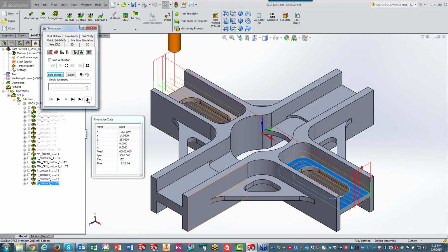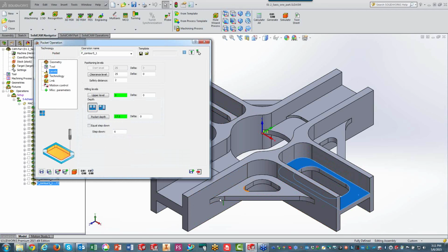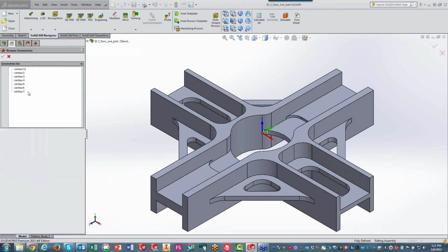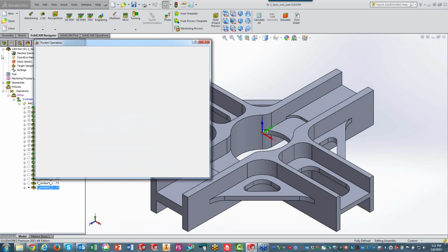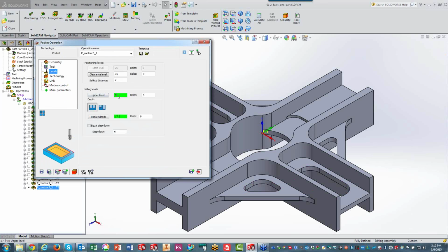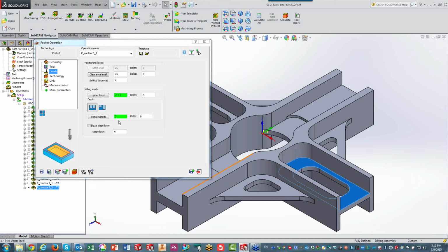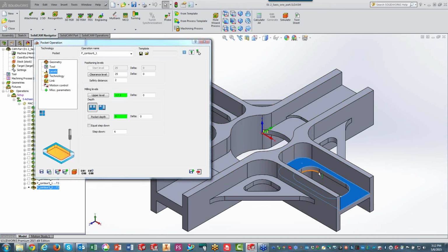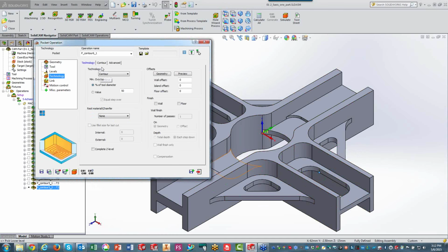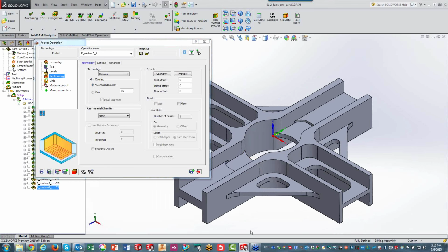That was done fine. And one more pocket over here is this pocket inside over here. So this time, again, save and copy. And this time I'll choose, not that one, but that one. Now this one, it's a closed pocket. Let me first change my levels. My upper level, since this is machined up until that point already, I can start from there. And my lower level will be up until that point over there. Okay, note my technology, there is no open pocket. Save and calculate.